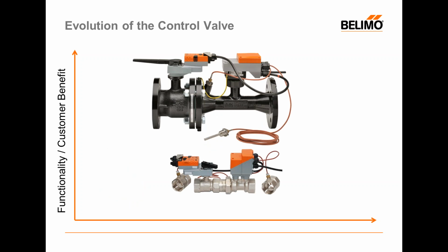So the Belimo Energy Valve has an integrated BTU meter that allows us to do our delta T management and allows us to be pressure independent using the flow capacities, but it also allows us to measure BTU. And when we measure BTU, that means we could control directly to how many BTUs are being produced. So we didn't like to control to the position because that didn't allow us to know really how much water was going to our coil.